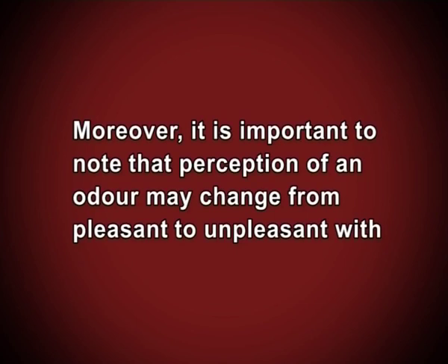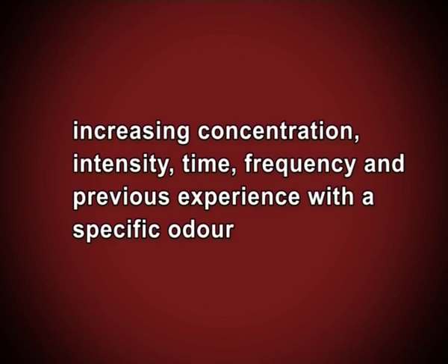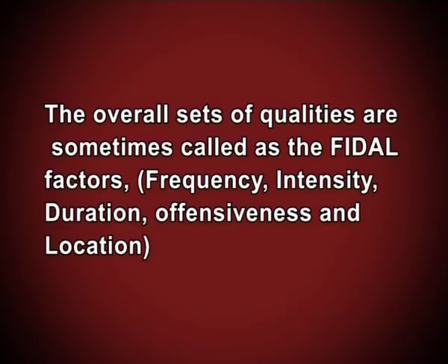Moreover, it is important to note that perception of an odor may change from pleasant to unpleasant with increasing concentration, intensity, time, frequency, and previous experience with the specific odor. All these factors are determining the response. The overall set of qualities is sometimes called the FIDOL factors, that is frequency, intensity, duration, offensiveness, and location.